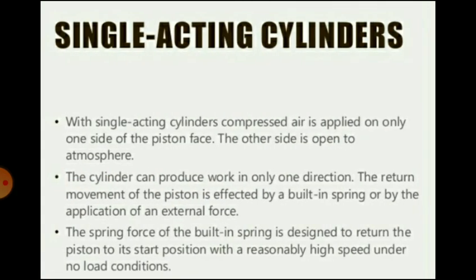Single acting cylinders: with single acting cylinders, compressed air is supplied on only one side of the piston face. The other side is open to atmosphere. The cylinder can produce work in only one direction. The return movement of the piston is effected by a built-in spring or by application of an external force.